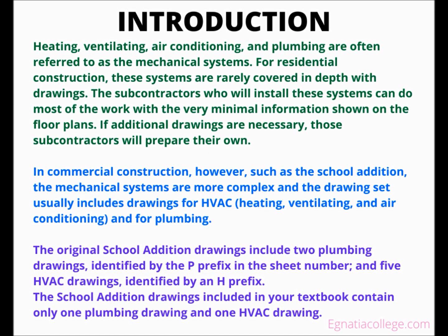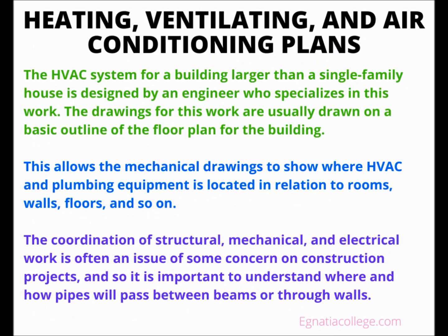In commercial construction, however, such as the school addition, the mechanical systems are more complex and the drawing set usually includes drawings for HVAC, heating, ventilating, and air conditioning, and for plumbing. The original school addition drawings include 2 plumbing drawings, identified by the P prefix in the sheet number, and 5 HVAC drawings, identified by an H prefix. The school addition drawings included in your textbook contain only 1 plumbing drawing and 1 HVAC drawing.